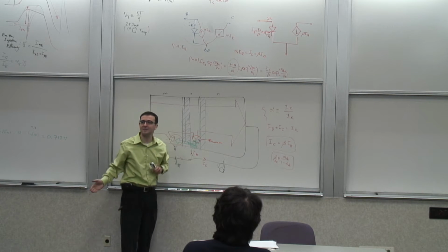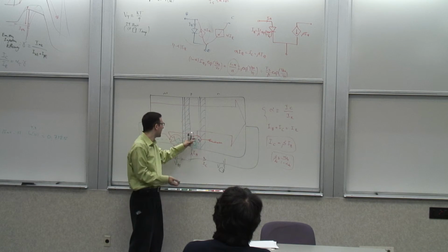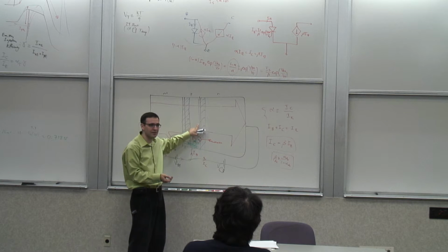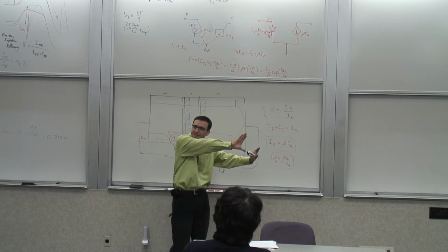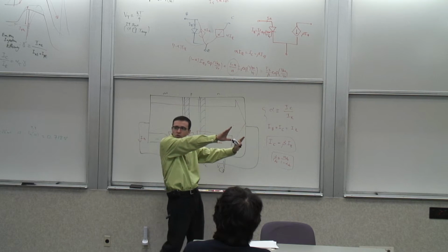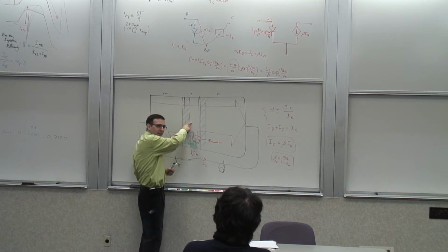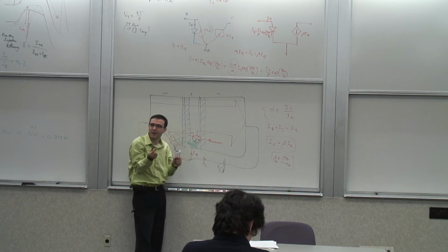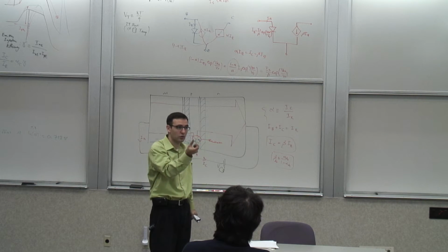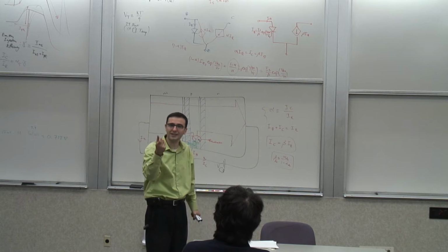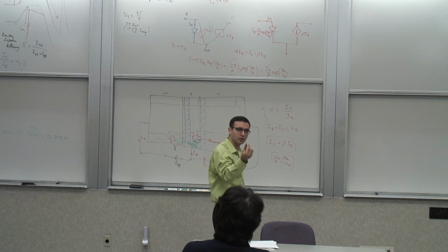And of course, this is also aided by the fact that the tail of this depletion region, the electric field's tail, is extended into the base, a little bit deeper into the base. So there's a higher probability of these guys making it across because I effectively make my base shorter. And we saw that the shorter base is better, right? So the effective base width is shorter.